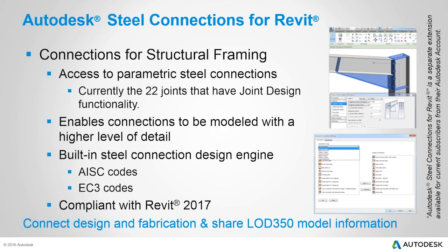And that means they obviously put a lot more detail into their Revit models. But don't panic, it's not going to undermine your jobs. If you have a look at the model, the image at the top right there, all the parts in blue, the cap plate on the column, the stiffeners, the haunch piece, the plate and the bolts, those are all one single 3D solid. They're not individual parts. There is no practical way to get a detailed view of any of those parts. Because they're not individual parts, they can't be called up on any bill of materials or schedule or list at all. It's just one thing called a haunch joint.